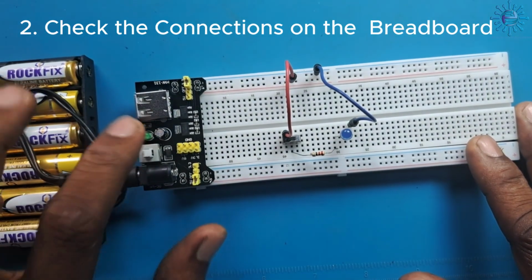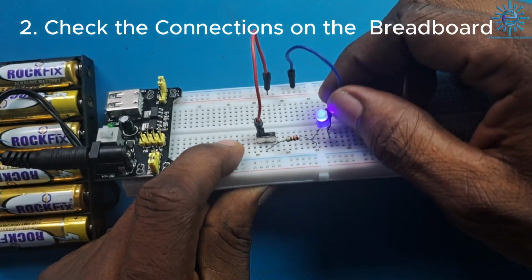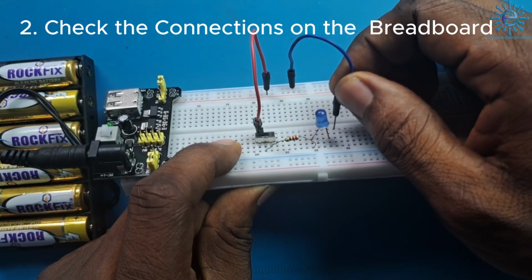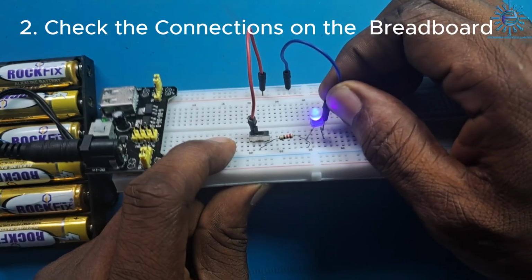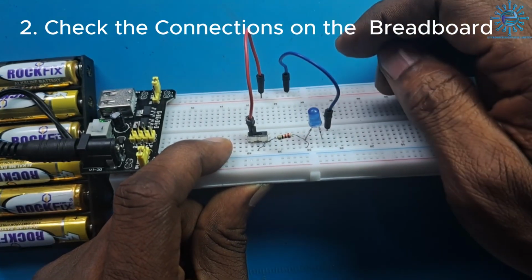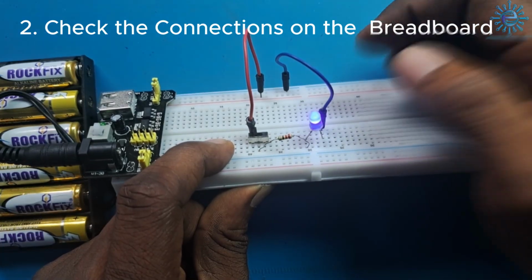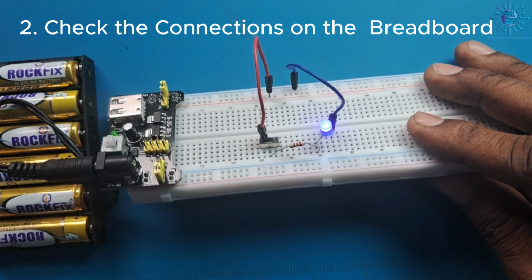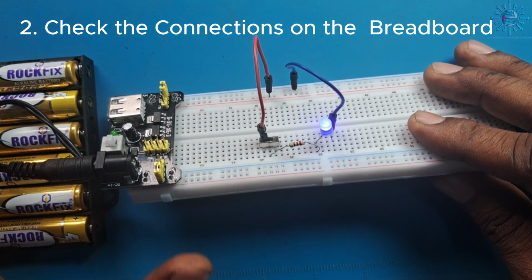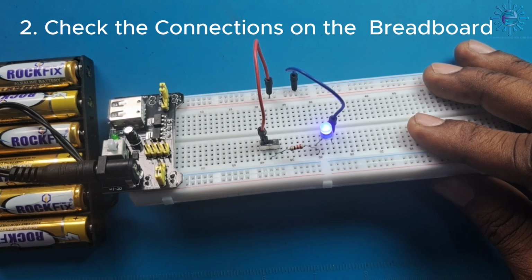Check the connections on the breadboard. So if in the process of our connection, I placed this jumper wire here instead of here, you can see that by removing it here and putting it here, the LED did not come on. But if I put it in the appropriate position, it comes on. So always make sure the legs of the jumper wires and components are inserted into the correct holes on the breadboard. Incorrect connections can prevent the circuit from working.